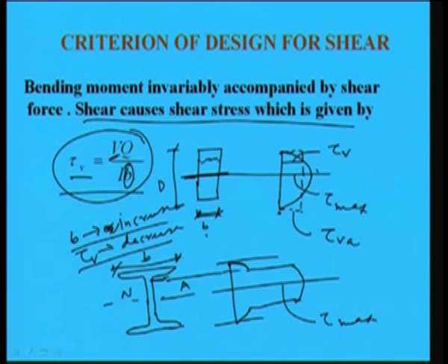Here it is important to note that in this portion the shear stress is very less, because here B, the width of the section, is very high, and a sudden decrease of width at this position is going to increase the shear stress suddenly. So, this is how it develops. So, you have to take care of all these things.